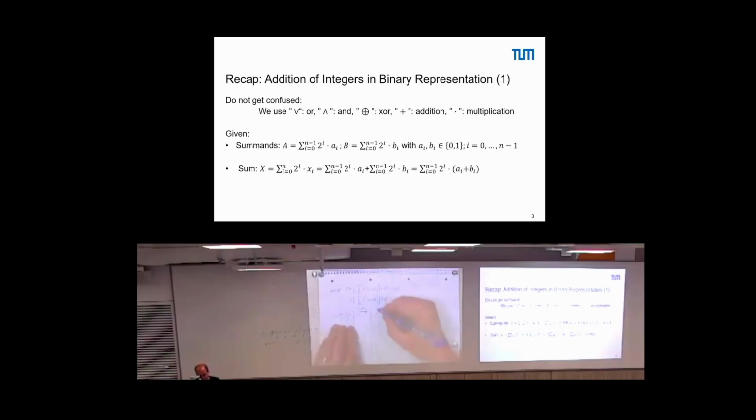So, what should be the decimal value? Here it's 0, 1, 1, 2, 1, 2, 2, 3. Right? Just adding up the bits in a decimal value. The interpretation in this binary formula: 0 is obvious 0. A 1 is a 0, 1. A 2 is a 1, 0. And a 3 is a 1, 1. Right? Just interpretation of this equation as a truth table.